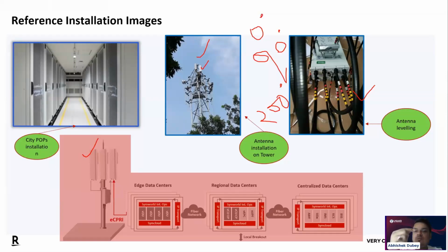So obviously you have to mark the labeling on the cables, so that there should not be any swap in the jumper cables. If there is a swap, it can contribute to losses in the coverage, because there is also ambiguity with the sector.